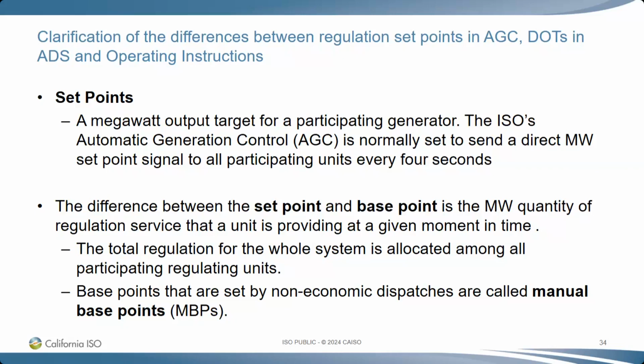Earlier I mentioned that when you're handing off to the person that's running the resource, that's something you need to know how to do. How do you put your resource on AGC? How do you take your resource off of AGC? What is the procedure for that? Have you practiced so that you're aware of how to do it, so that when you're in an emergency situation where you do get this operating instruction, that's not the first time you've had to try and figure it out, because time is of the essence. That's an important thing to have set up.